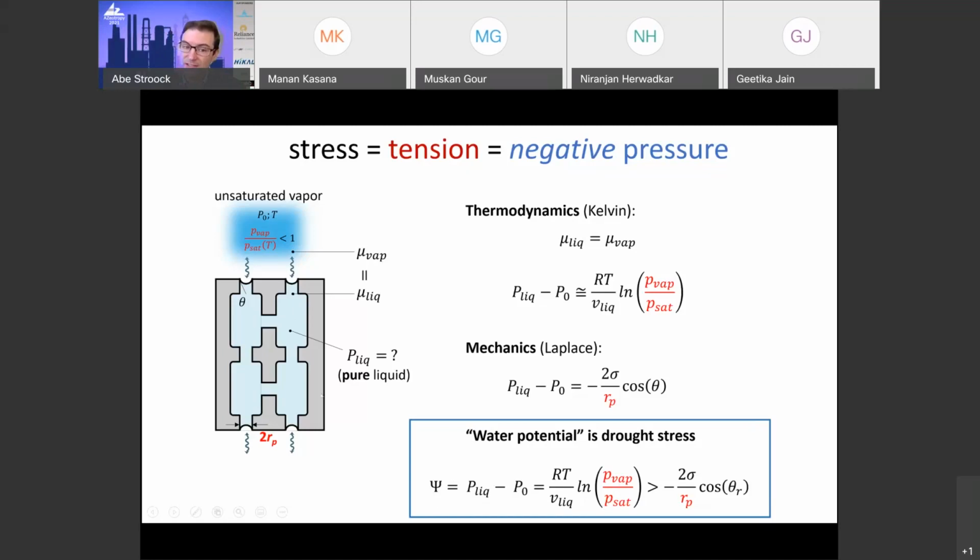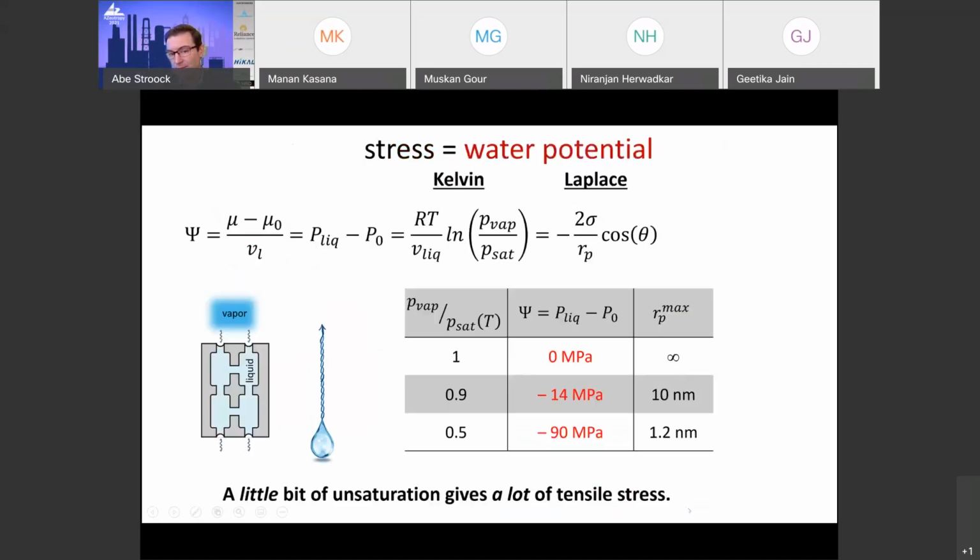And for this system to work, the meniscus must remain stuck at the interface. And so this has to stay less than, in magnitude, the maximum capillary stress that can be created by this small scale pore. And so this is where this nanoscale pore becomes important.